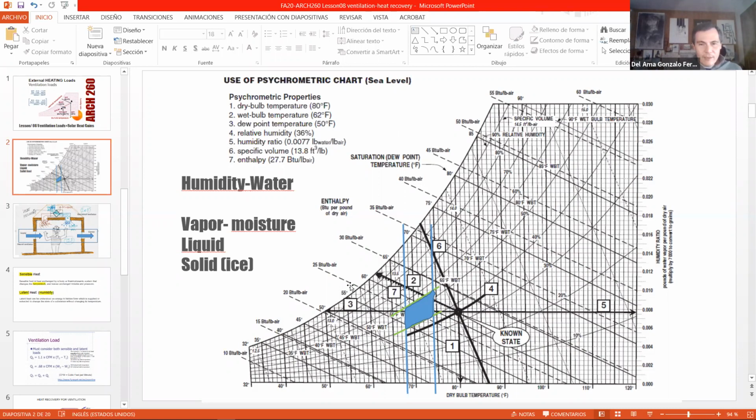So that's why we have this comfort range. Within this comfort range, these temperatures, 100% of people are under comfort conditions. Someone might be more comfortable close to 74, and others might be comfortable close to 68. But below 68, everybody feels cold. Above 74, everybody feels that it's warm or too warm.